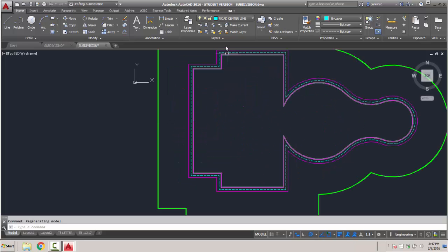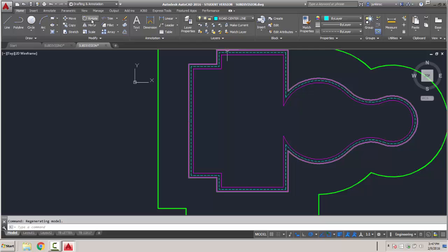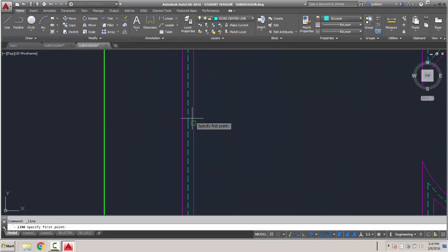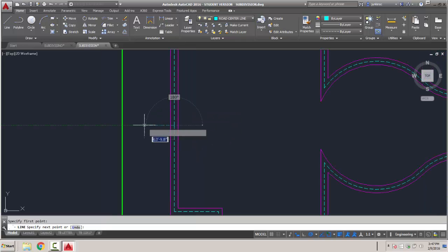Road center line. We're going to put an exit road in here by just finding the center point, which is right here. It's actually an end point because remember we mirrored that. Bring it over until it is perpendicular to that line. And then we can offset this a distance, hit enter. We're going to offset this 8 feet and 8 feet on the other side.